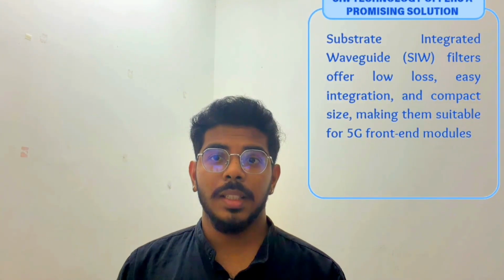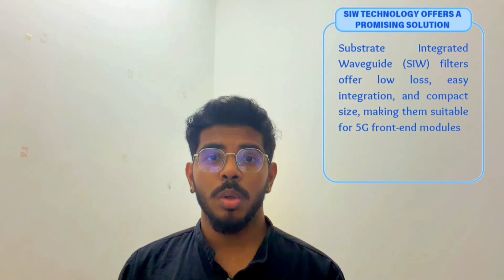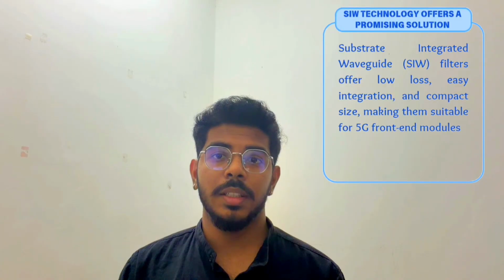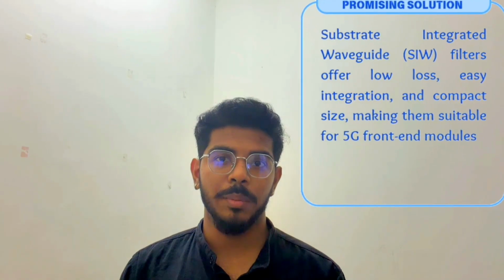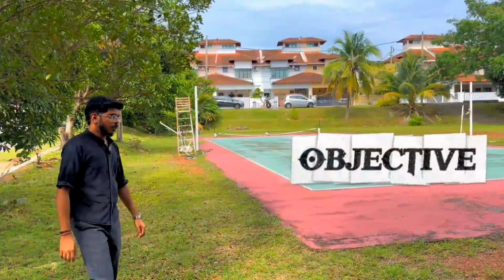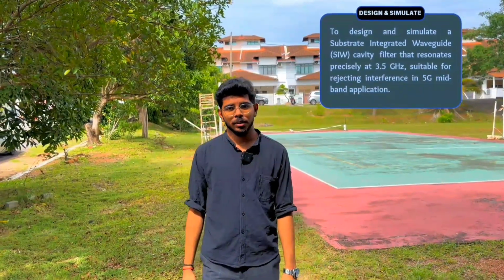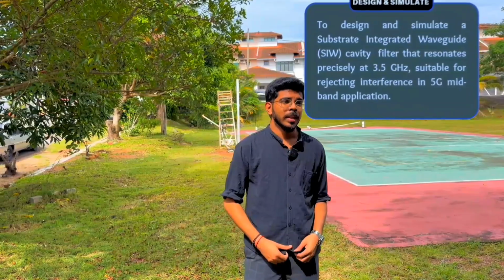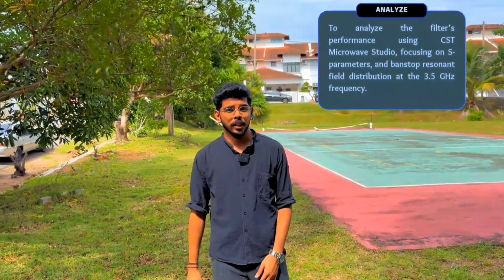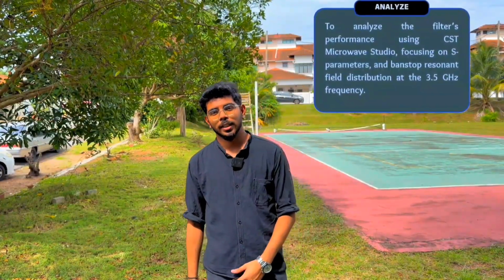And then we have the SIW, which is the substrate integrated waveguide filter, offering low loss and easy integration, and also a compact size that makes it suitable for 5G front-end modules. So the main objective for my project is to design and simulate a cavity bandstop filter to trap the 3.5 GHz frequency, and also to analyze the cavity bandstop resonance response using S parameters.